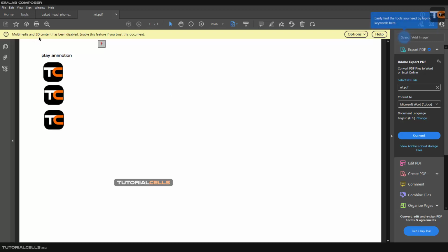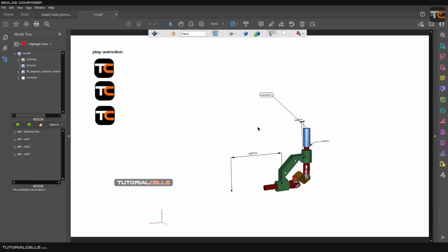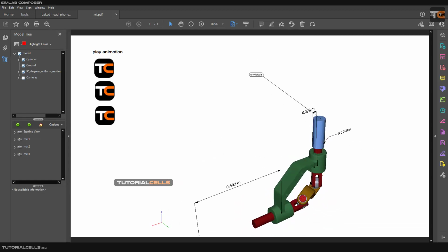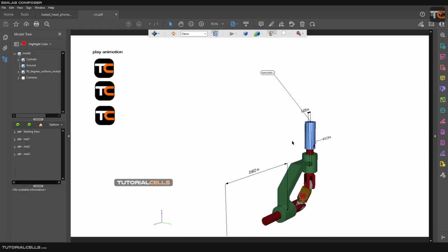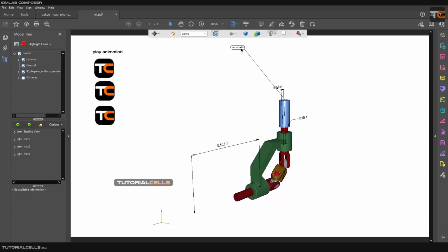First, you have to allow the 3D PDF to show your PDF. Trust this document always. And one click on your 3D content. And it's ready. Interesting. You can click and drag, right click to zoom out and in, press right click and left click together and drag to pan. And as you can see, this is our annotations, our measurements.